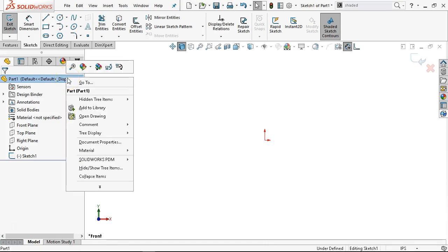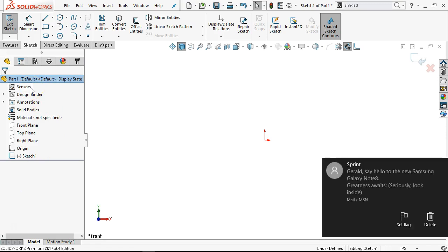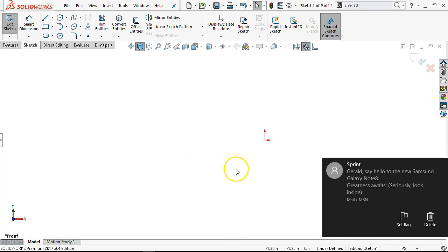All right, so dynamic reference and parent and going to the child, those are both right clicks. If you haven't gathered yet, from Tuesday night, this is pretty intensive right click. So the right mouse button, whatever you're hovering over is going to have a context menu that is fairly specific to whatever it is that you were hovering over. Sensors we're not so much worried about, but I can set a sensor that says if this part gets over 500 grams, warn me.